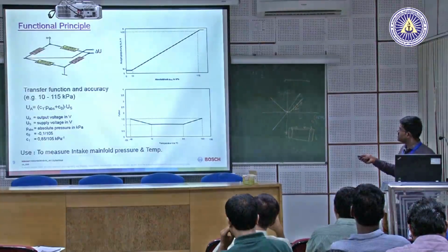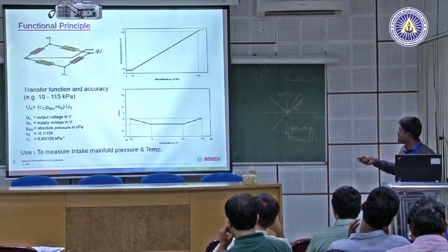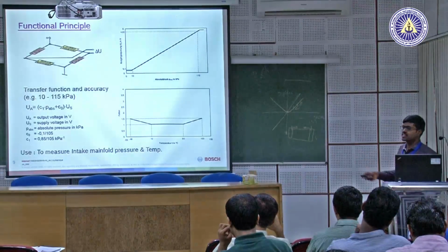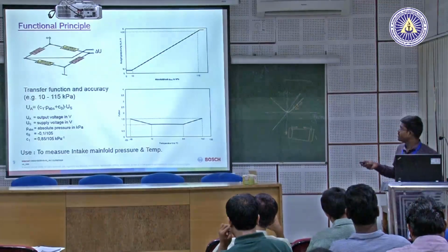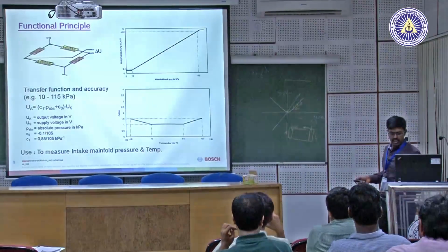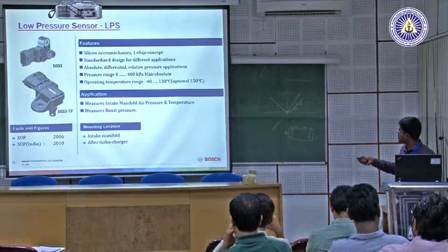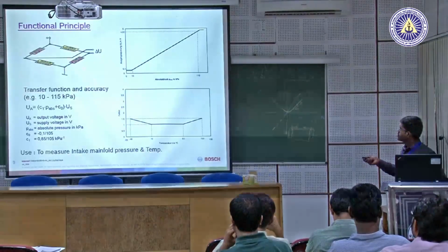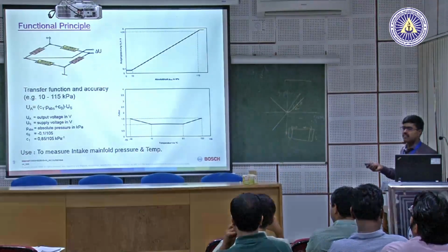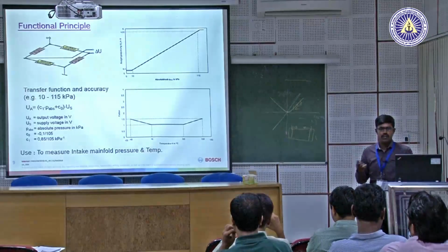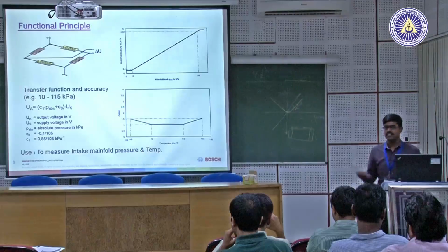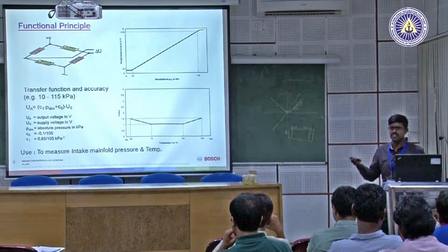Here you see we have two chambers, in the automotive sector I am talking about. So, we use pressure transducers here. This is one zone and this is another zone. For an absolute sensor, as opposed to differential and relative pressure sensors, the lower zone will be fabricated in vacuum, meaning it does not have any effect from pressure.